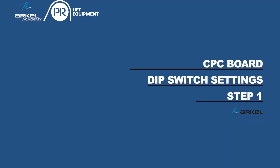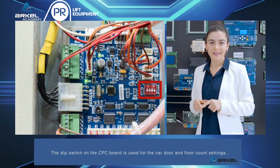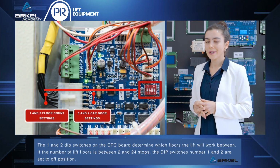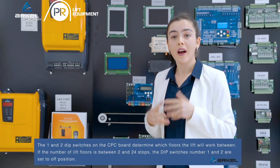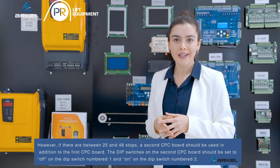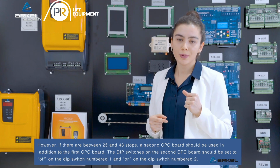CPC board dip switch settings. The dip switch on the CPC board is used for the car door and floor count settings. The 1 and 2 dip switches on the CPC board determine which floors the lift will work between. If the number of lift floors is between 2 and 24 stops, the dip switches number 1 and 2 are set to off position. However, if there are between 25 and 48 stops, a second CPC board should be used in addition to the first CPC board.